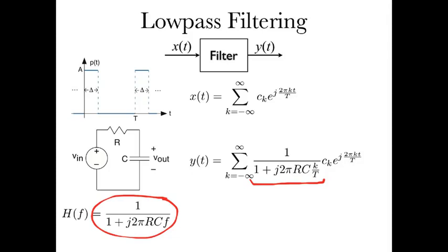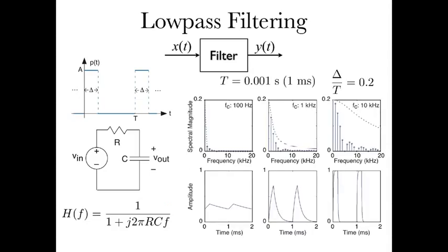Well, this reconstruction, to say the least, we can't do analytically, so this is where you call upon a computer that can evaluate these things and add them up. And here's what you get. Really kind of interesting. So, first of all, I had to pick what T was, the period of our periodic pulse train. I picked 1 millisecond. What does that make the fundamental frequency, the first harmonic of that signal? What is that frequency?